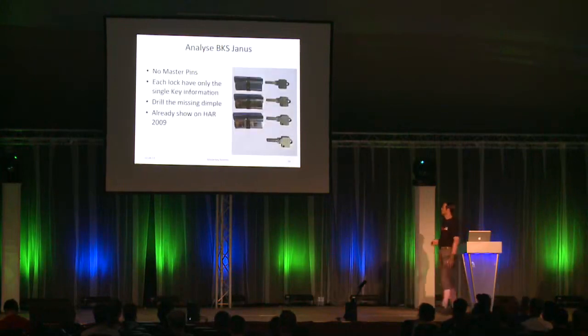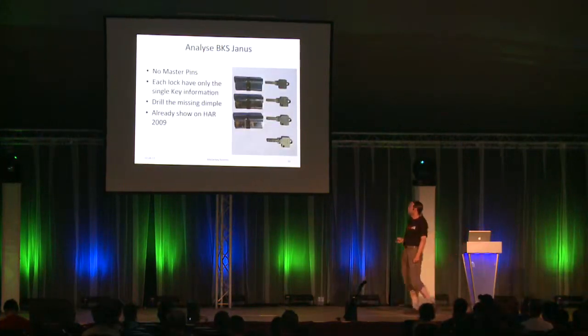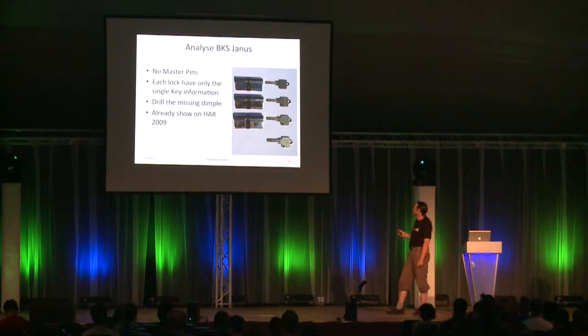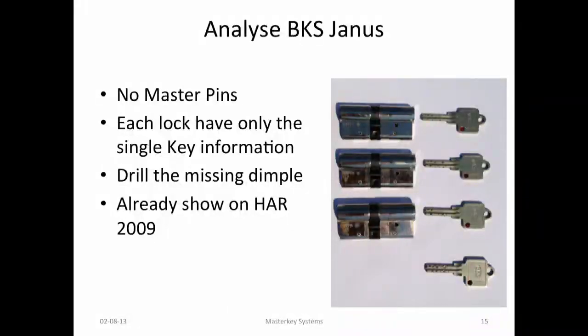This is a different system. We already analyzed this here from Ray and MA and Zahar. This has multiple pin positions. So each lock has only the pins inside from its own key. This system doesn't have any master pin, so it just has these different pins. And I made this master key myself. You just use a single key, and mill each position that you don't have.